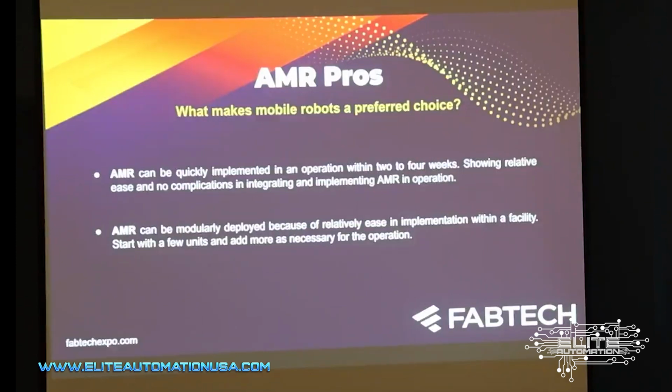The robot fills up all pallets available, and then the robot just has to stop, and then the whole line stops because there's not somebody there to service the robot. However, when going to an AMR type of system, that is a discrete signal sent to the AMR system to call for the AMR to come. Right, the AMR then makes a calculated decision on picking up that component.